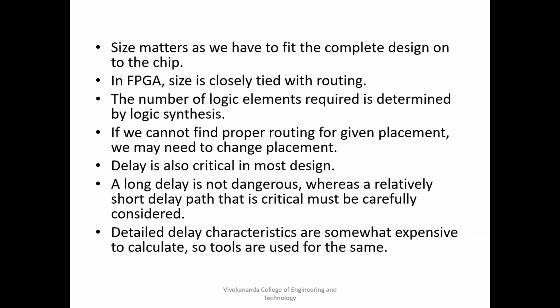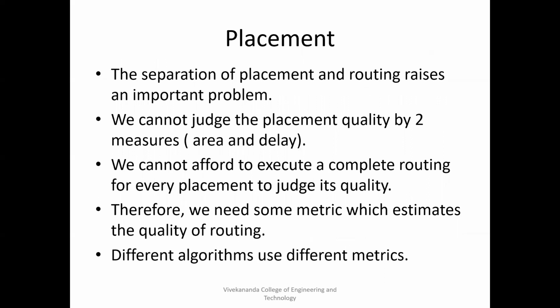Or else, when you're placing, you should know which components have to be connected. Those components to be connected, you cannot keep at either ends of the placement or of the chip, and while routing you have to connect from one end to another. That would cost you on the delay. So those things have to be taken care of while doing placement and routing.